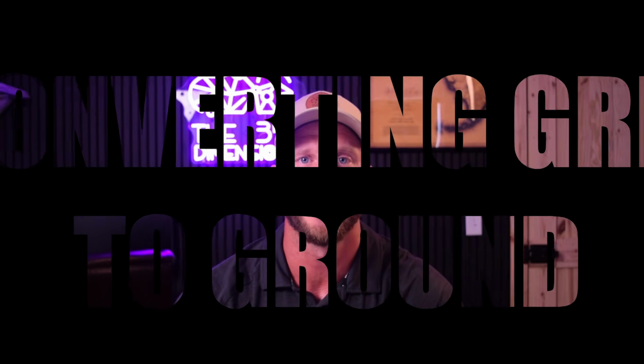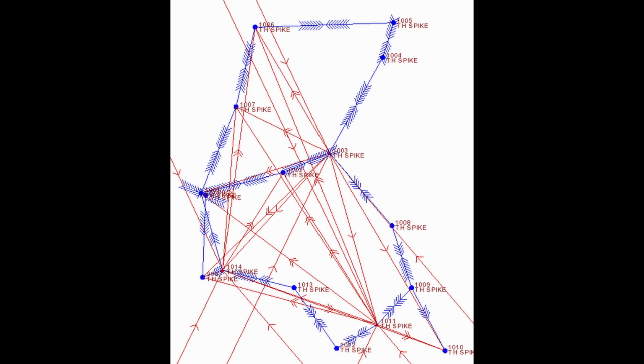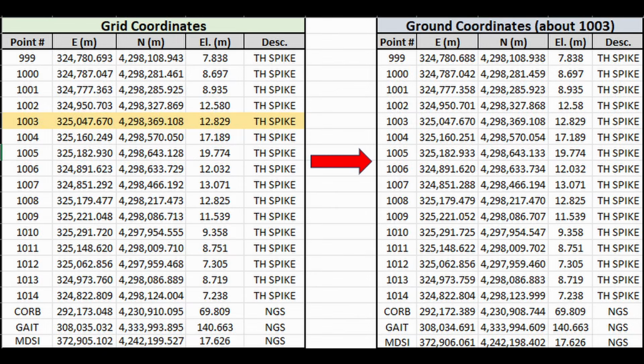So how do we go about converting grid coordinates of a project to a ground-based coordinate system? We typically pick a point in the middle of the project that has an approximately average elevation and obtain the combined scale factor for this point. We can call this our scaling point. We then scale all the northings and eastings of the surrounding points using the inverse of the combined scale factor. Typically around that scaling point, but it's not necessary. Scaling about 0 northing and 0 easting is a common practice as well.